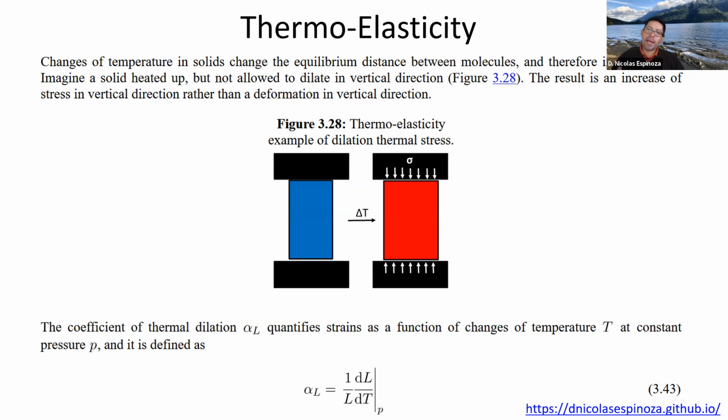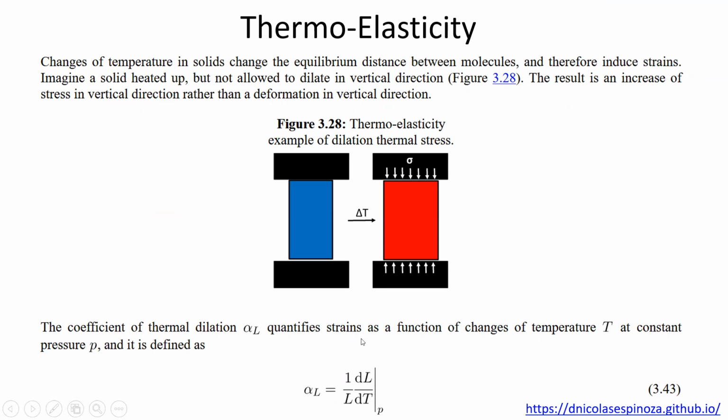a relatively soft rock like a sand in a young sedimentary basin like the Gulf of Mexico or like the North Sea, as those are very good targets for injection, will develop less thermal stress than a very deep rock, which is very stiff, like a deep carbonate or a very stiff shale or a granite. So this also depends. It's not only the change of temperature, but also the thermal dilation coefficient and the stiffness of the rock. But a temperature change of, let's say, 30 degrees Celsius, will that generally cause some problem?